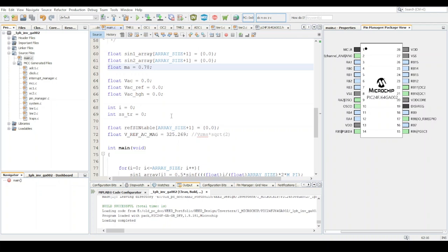Or even without your sensor being wacky, if it's just a normal sensor and your output voltage signal looks kind of strange, say it's got spikes, it might pick up one of those spikes as the maximum, and you just basically max out at 0.95 amplitude MA value. Or worse, it will oscillate from that to low, high, low, etc., which is quite undesirable, as you can imagine. So that's essentially the first method, which is the easier way to achieve the closed loop control of the inverter, and it's got positives and negatives.